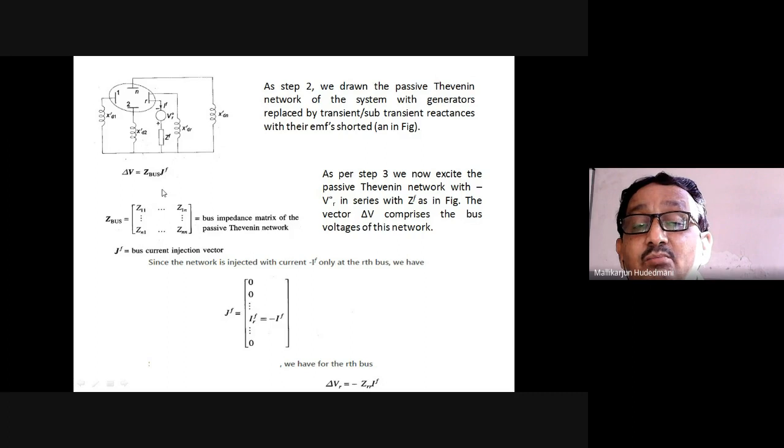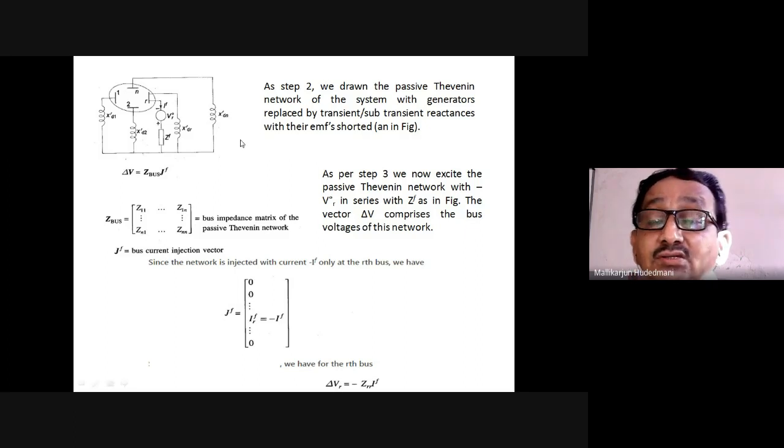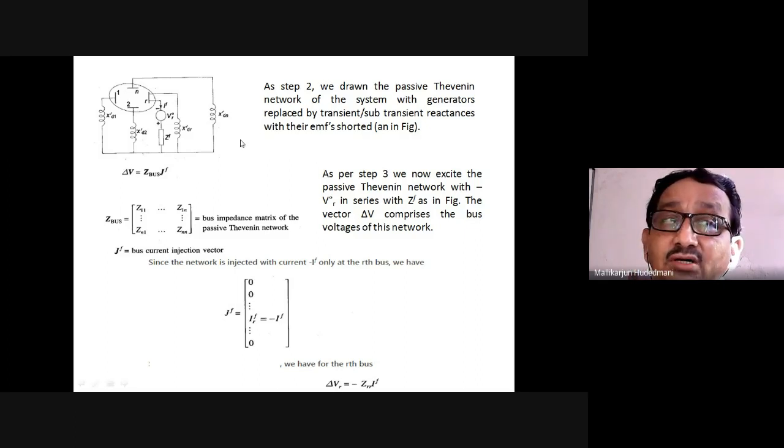And it is multiplied by Z bus of the system. Now here comes Z bus of a system to compute post-fault voltages of a given power system. Now you got to know here, whatever the study we have done, formation of Z bus by building algorithm from scratch, element by element addition, either in the form of a branch or in the form of a link, such an activity constitutes Z bus of a given power system in steps. So that was an activity we have already learnt.